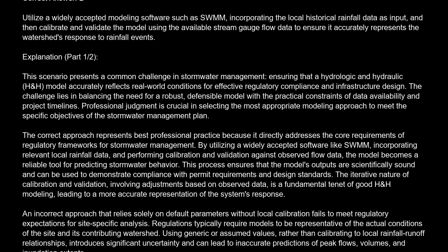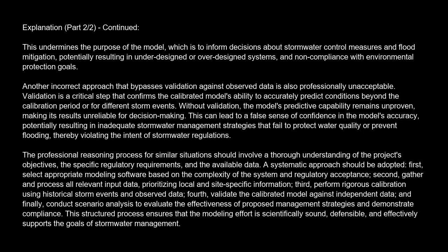Using generic or assumed values, rather than calibrating to local rainfall runoff relationships, introduces significant uncertainty and can lead to inaccurate predictions of peak flows, volumes, and inundation extents. This undermines the purpose of the model, which is to inform decisions about stormwater control measures and flood mitigation, potentially resulting in underdesigned or overdesigned systems and noncompliance with environmental protection goals.